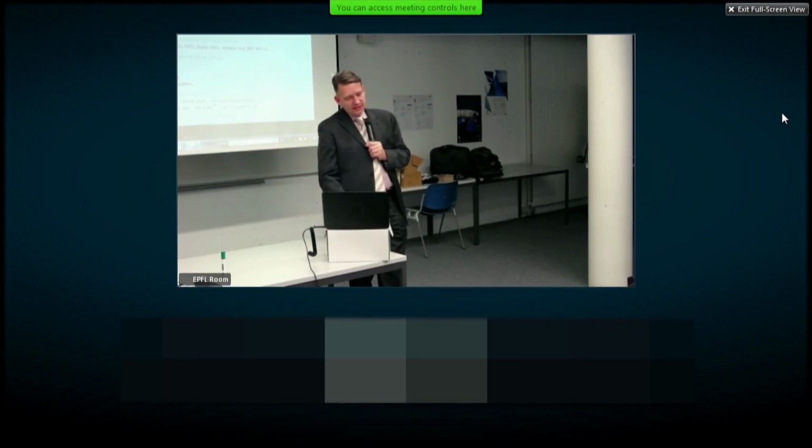The nature of the information: is it analog? Is it digital? Is it wireless? On the analog side, we're essentially talking about some signal, some voltage, and there's been a lot of work done on ADC, analog-to-digital conversion, and the opposite is digital-to-analog, right? Depending on how many bits you have available, you're going to have some discretization errors. A purely digital interface we refer to as DIO, digital input-output. And then, of course, wireless, the 802.11 standard, which is very important these days.